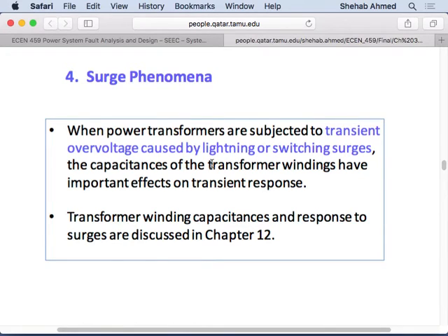So these phenomena, again, current being placed on a conducting material is charge, right? On a material. And remember, all our devices, all our power transformers, transmission lines, everything has to be protected so humans can be close to it and touch it. So all the equipment is typically grounded. Now I have these huge charges being placed because of these transient phenomena, and I have my equipment that is grounded. It's like creating a big capacitor, right?